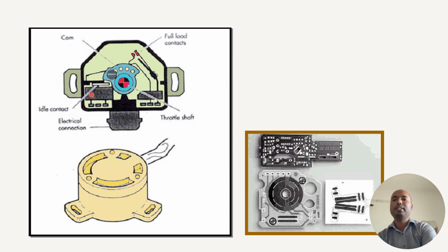It is nothing but a contact breaker. While in the idle condition, these cam lobes will compress this contact breaker. So the 5 volt DC power supply is directly given to the contact breaker, and again the 5 volt DC is given as an output. This means the ECU can recognize that there is no acceleration, so idling is required.